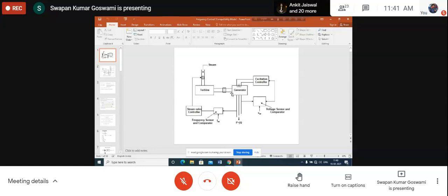So you see that the response time is of the order of half a cycle only. And how much is half a cycle? For 50 hertz frequency, cycle time is 20 millisecond. Then half cycle time is 10 millisecond only. That means within 10 millisecond, your control will be applied.